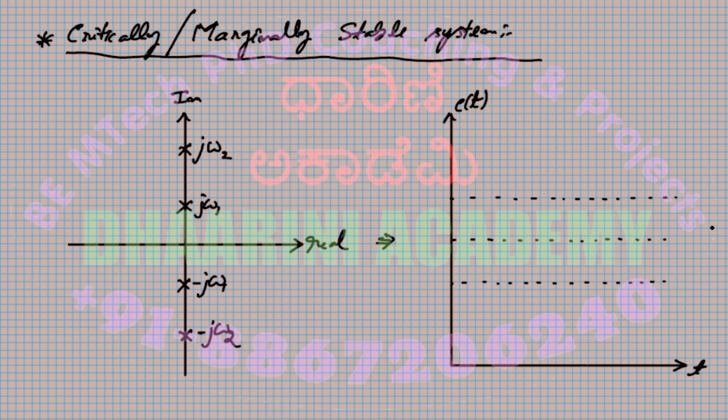Its amplitude is neither increasing nor decreasing at a given point. So constant oscillations are the example for a marginally stable system. It's going at the same pace continuously, because the system is marginally stable. Its output is not going to infinity, so you can call it stable, but it is not properly stable because the output is not fixed. So that's what we need as a condition.